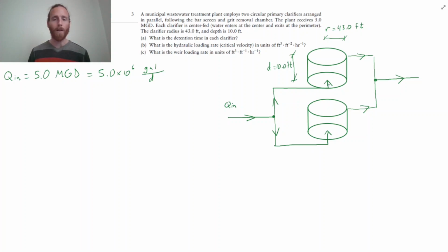And you have water that comes in from the bottom and very slowly flows up. And the goal is that it flows up so slowly that the particles in it settle down faster than the water is flowing up. And so you get cleaner water flowing up to the top, and sludge, which forms at the bottom and is removed at the bottom.